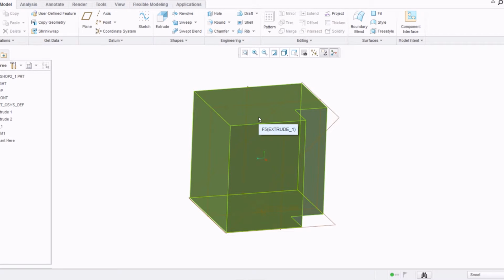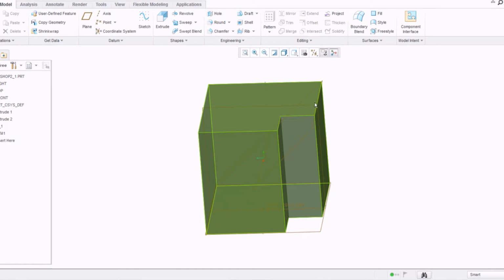And this is quite useful because if you look at our engineering sketch, you'll see that our feature starts exactly 5 inches at a 45-degree angle from the top right corner. So what I can do is create a second plane at a distance of 5 inches from the first plane, and extrude down towards the part. And let me show you what this looks like.